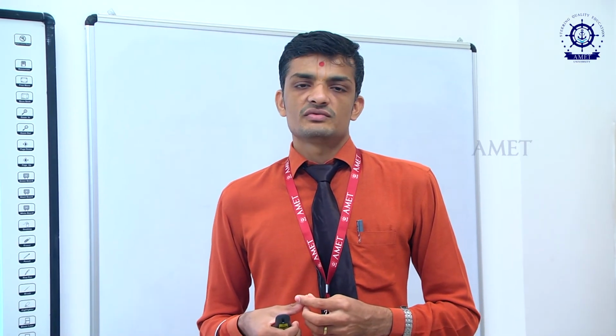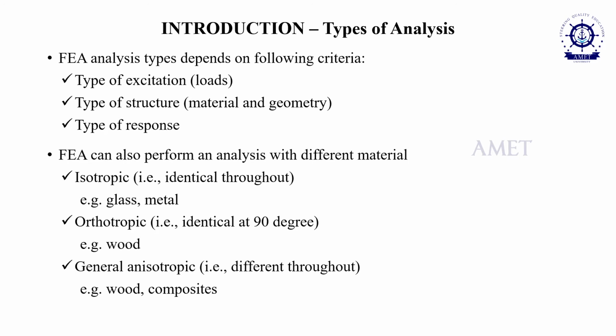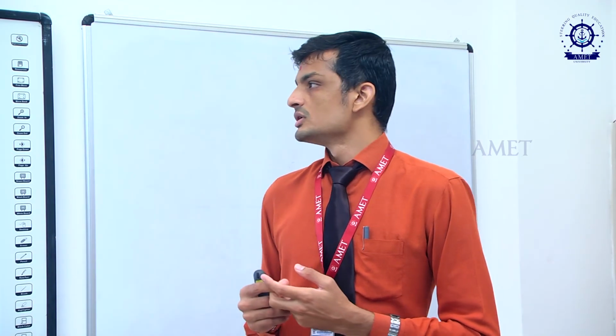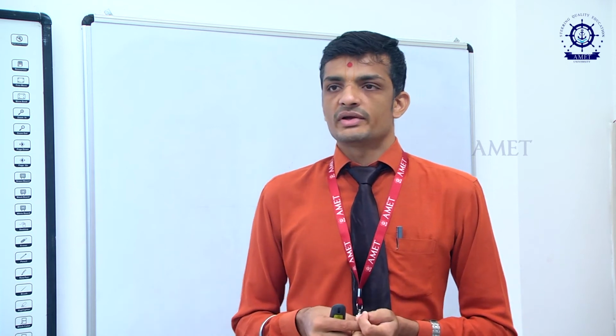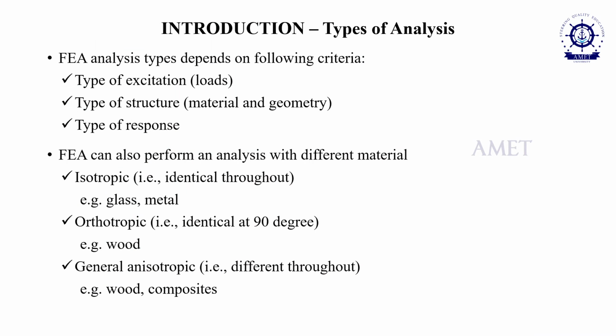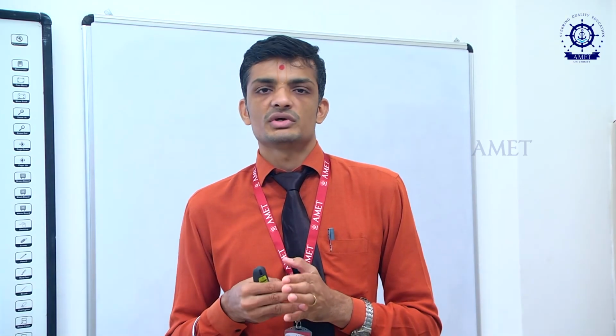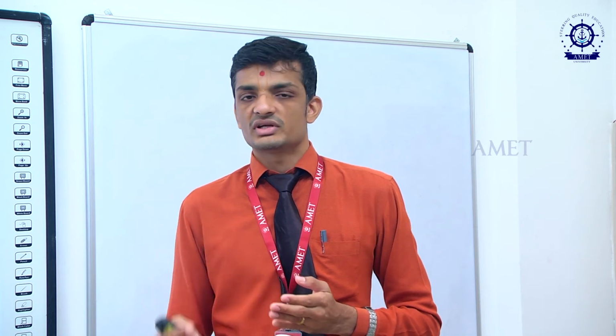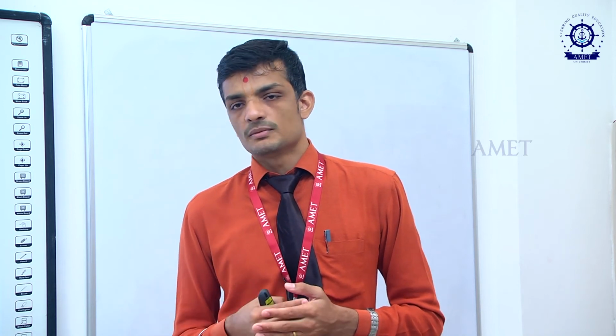Let's further understand what are the different types of materials we use, and what are the main parameters on which the analysis depends. The number one parameter on which the analysis highly depends is what sort of load you are applying. So if it is again a cantilever beam problem, if it is a point load or the uniformly distributed load or uniformly varying load, under all the three conditions you are going to have a different response, correct? It's not going to deflect the same in all the three conditions, three different responses will come.